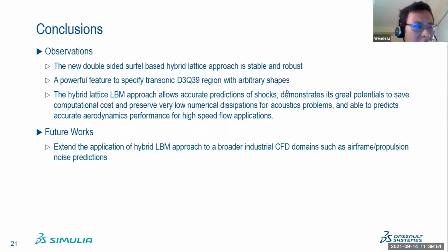There are other sources. For example, if we use a fractional step lattice Boltzmann method, the fractional step with displacement of 1 will also introduce dissipation. I think this has been discussed in a paper, and there may be other sources of dissipation for the D3Q39 lattice itself, but currently I'm not sure about that part.